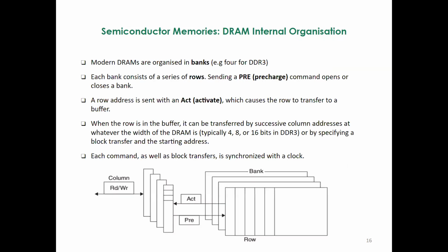We discussed this one as well in more detail, the control signals and lines which are used to either enable a particular row, and then you select a particular column, then you can read either a byte or a word from your memory by specifying appropriate signals for the rows and the columns.